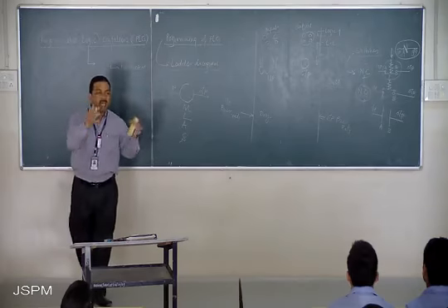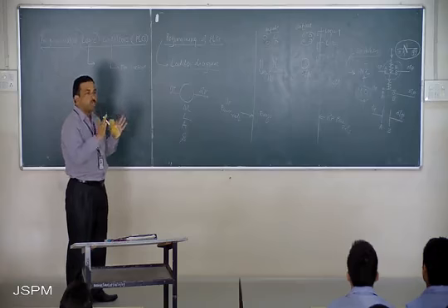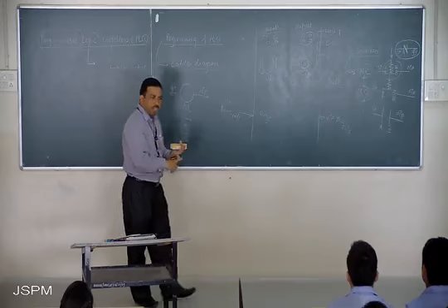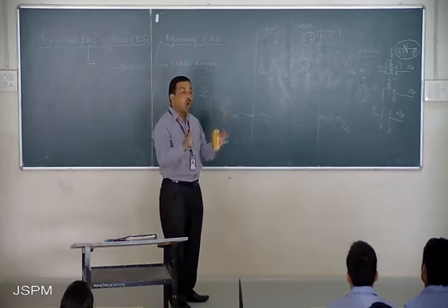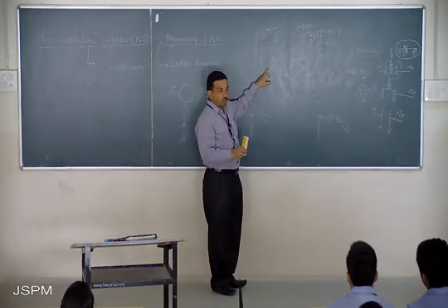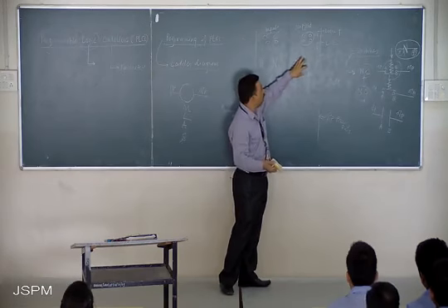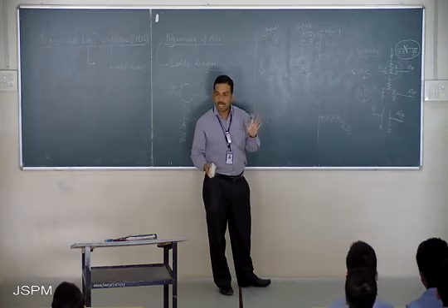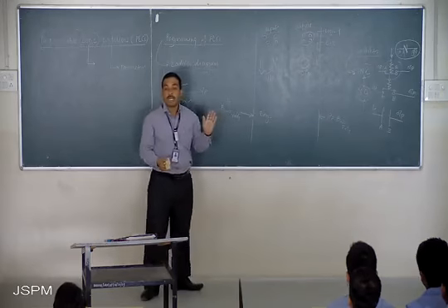So if you see any ladder diagram, on the left hand side you will find a combination of normally closed and normally open switches, irrespective of what type of input is there. That means either it is a temperature sensor, velocity sensor, displacement sensor, or flow sensor, all can be represented in terms of only normally closed or normally open switches. And whatever your outputs are, it may be solenoid, motor, lamp, alarm, all will be represented in terms of a circle. Are you clear, everybody? Okay, so these are nothing but the different components of the ladder diagram.